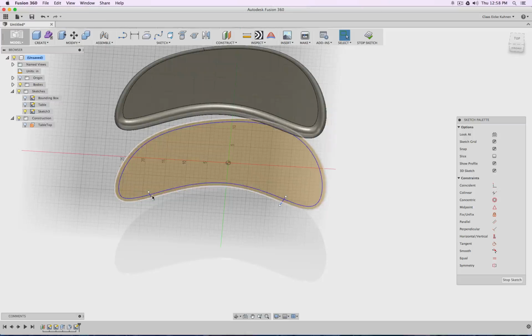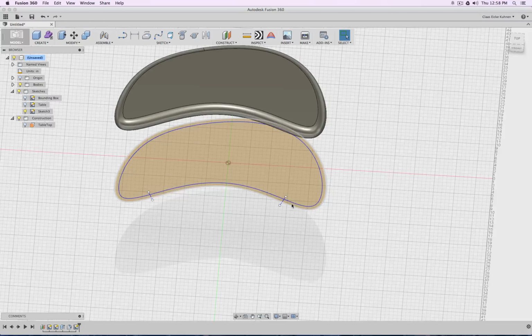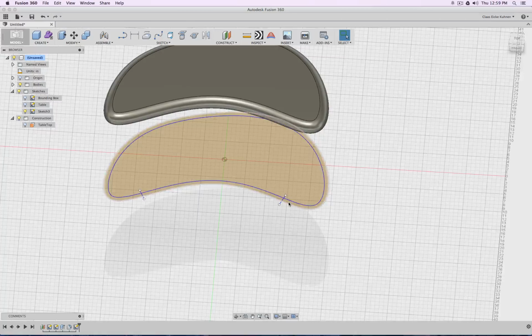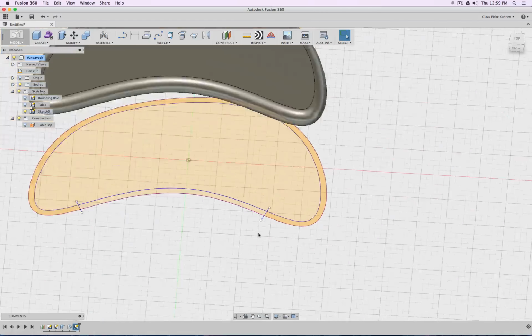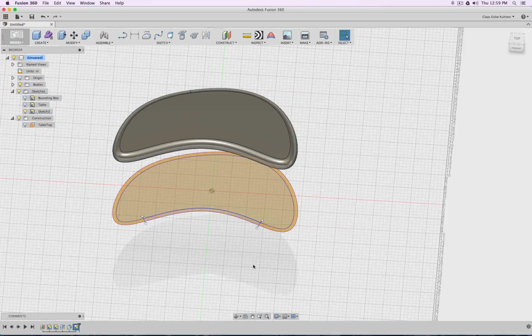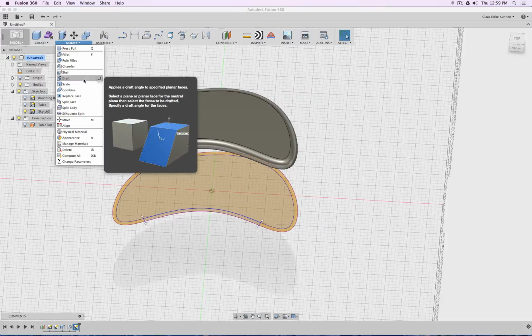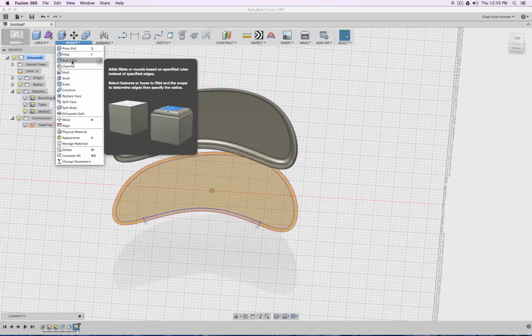And why did I actually draw these 2 lines? Well, these 2 lines help me, let me try to select this area. There, I have it selected. It helps me to cut off the outer ring into 2 segments, so this one and the smaller segment in between. And then what I have selected now, I can simply extrude up.